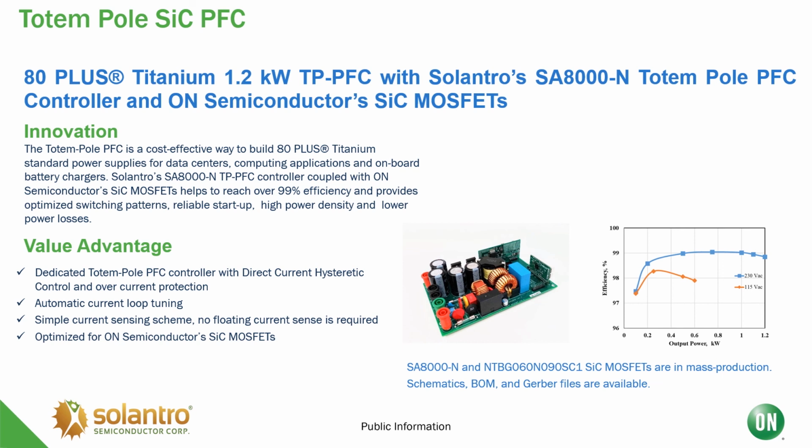This one specifically used our 60 milliohm 900 volt SiC MOSFETs. We were able to create this, which meets the 80 plus titanium standard, and we are able to reach an overall 99% efficiency and provide optimal switching patterns, reliable startup, and a very high power density.